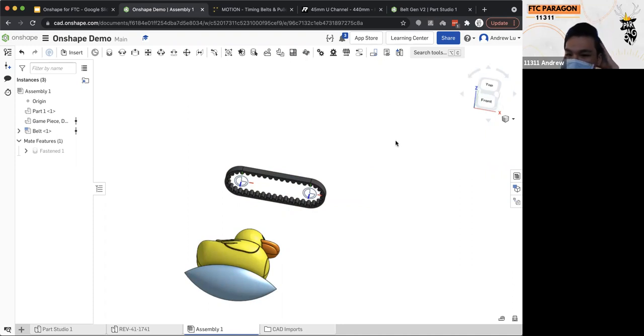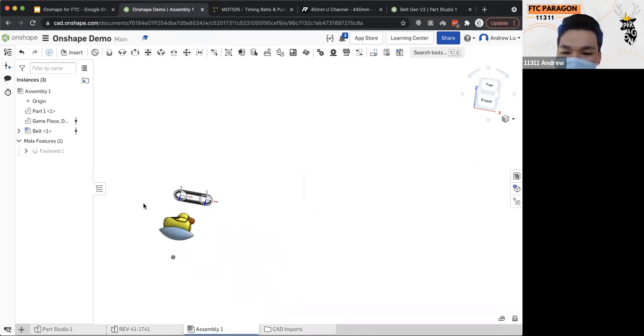Okay, first question, there's probably not a way to sync Fusion 360 assemblies and Onshape assemblies, unfortunately, because they use different file models. Like from Fusion 360 to Onshape, you have to export it and import it as a STEP file because that's sort of the universal file for these. And from my experience, the assembly constraints don't go over. So for example, how to join parts together for building a robot.